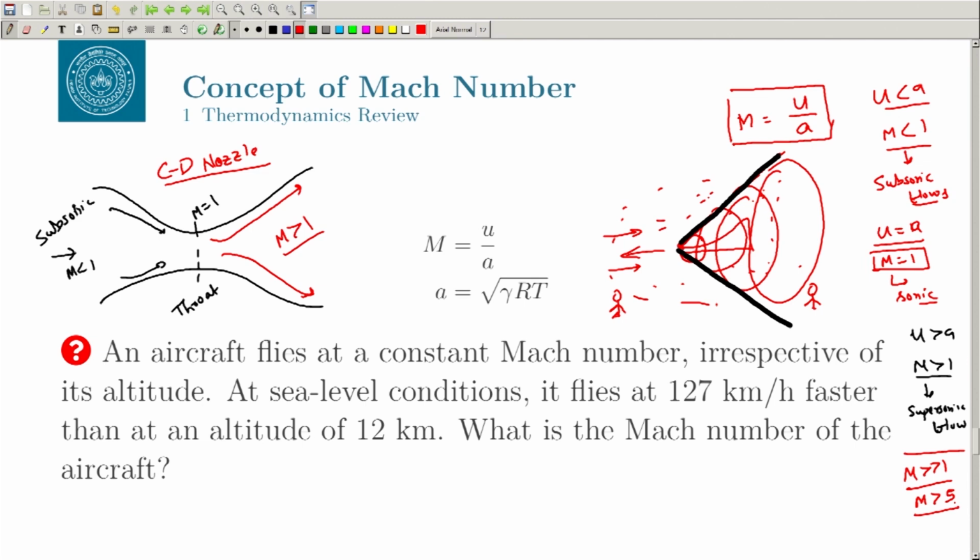Because of these things, these flows are kept in a separate category, which is the hypersonic flow. Here, not only the aerodynamics, but the thermodynamics also becomes very important. What we have been saying earlier, that the perfect gas equation may not be valid, applies here, because you will have reacting flows.